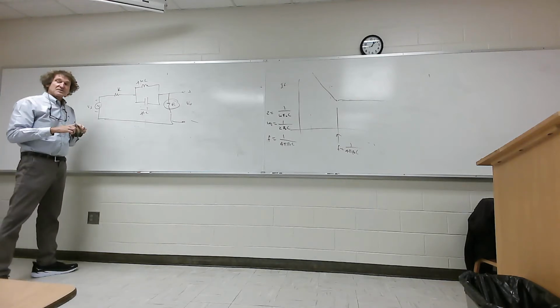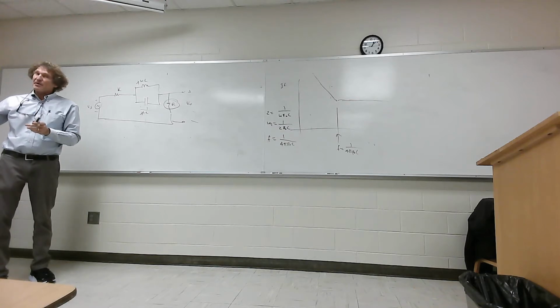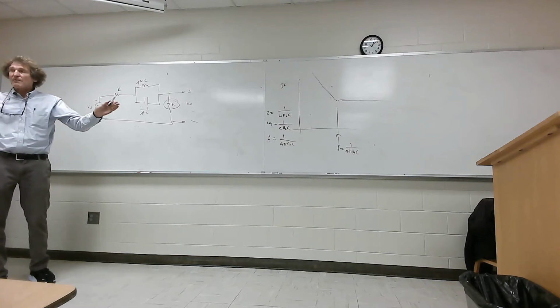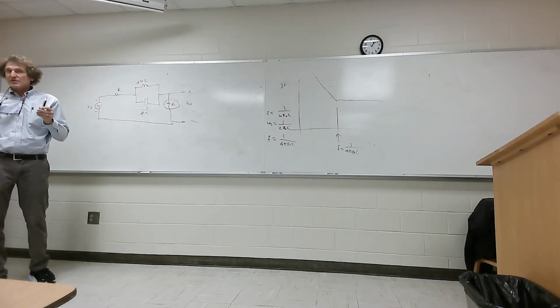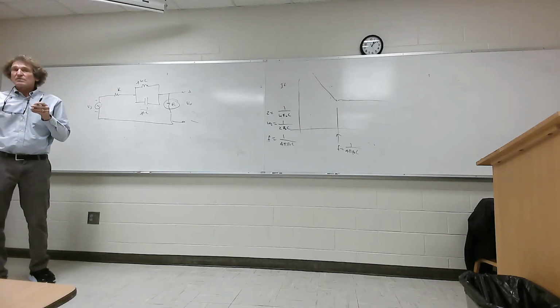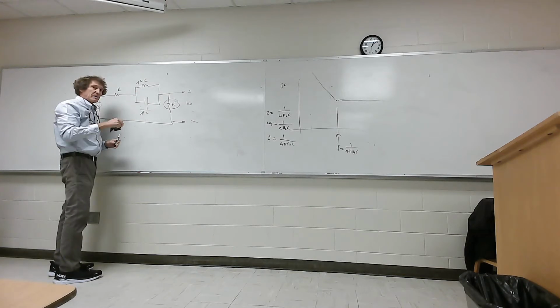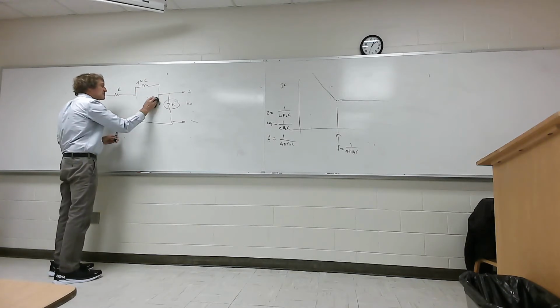What if I had this? Y'all follow me on this. If they're in parallel, LC in parallel, at resonance, it's basically an open circuit. And then the further off resonance you get, and we'll talk about the Q later, the more it looks like a short circuit. Y'all hear me? At DC, that inductor looks like a short circuit. At extremely high frequency, the capacitor looks like a short. So now for this.